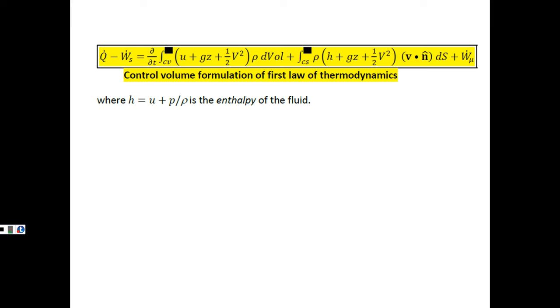So we're probably never going to have to actually use this equation for problem solving in this class. But as you've seen throughout this class, we go from a control volume perspective into a differential form. So we started out, before we got to Navier-Stokes, doing momentum transfer this way, right? And we flipped it into a differential form, which was much more compact and easier to work with to get to Navier-Stokes. Here, we're also going to move into a differential form, only now we're going to be considering this differential energy equation. So this is the all-encompassing equation that describes heat transfer as a function of time and location.